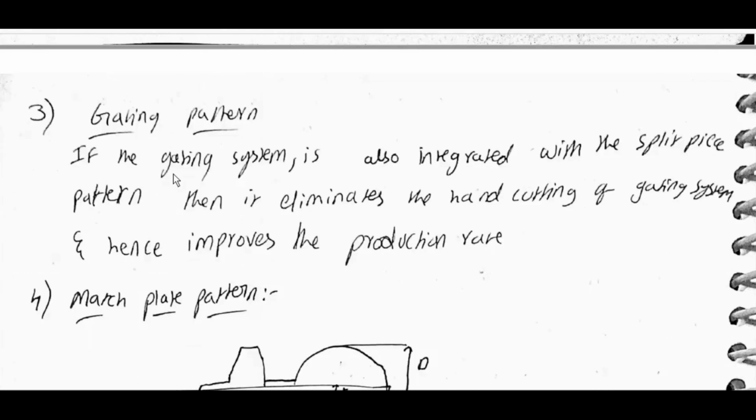Gating pattern: if the gating system is also integrated with the split piece pattern, then it eliminates the hand cutting of the gating system and improves production rate.